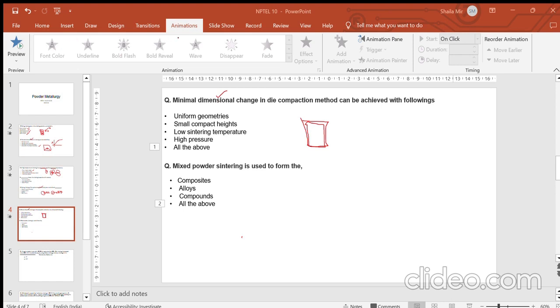You have to achieve a density which is near the theoretical density, that is what is required from powder metallurgy. So after sintering you achieve 86% of the theoretical density, while after compaction the green density is 55%.